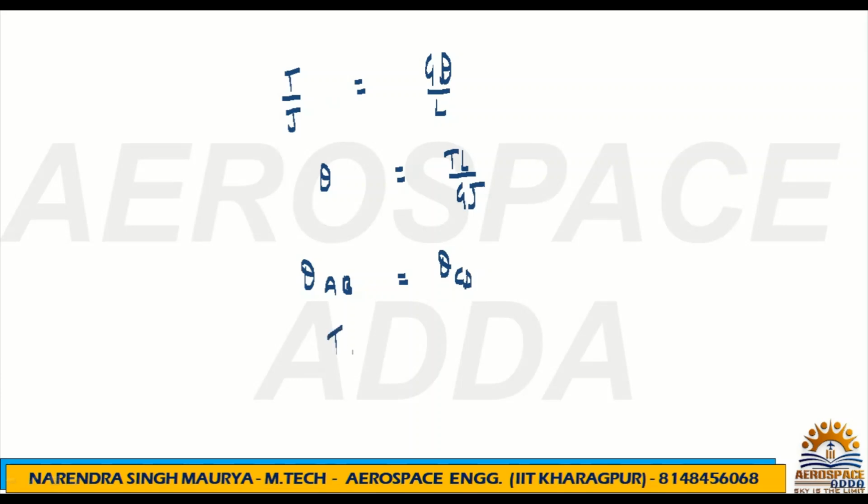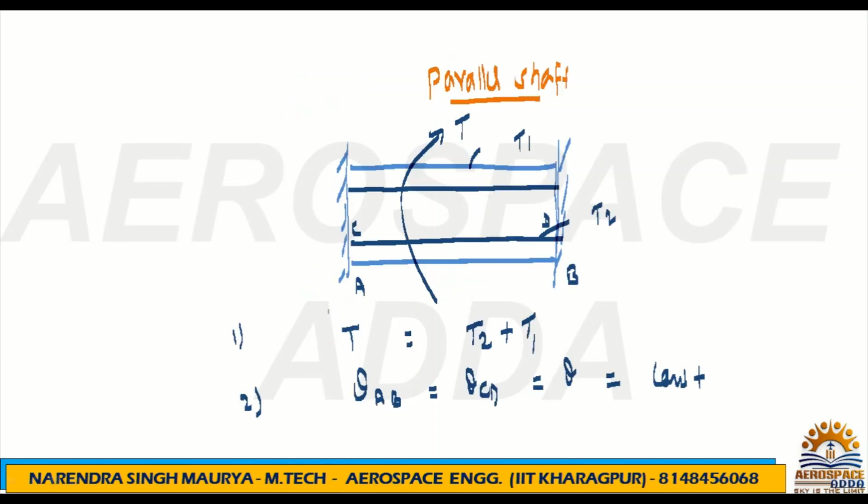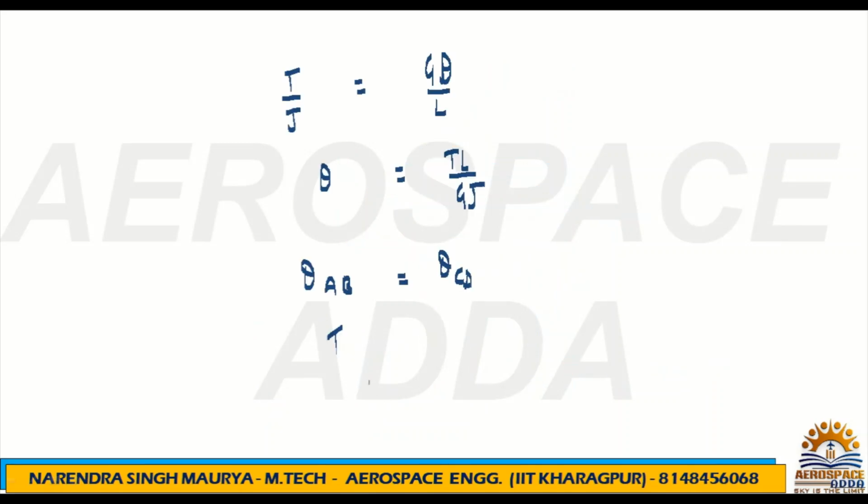First, the AB shaft is the external shaft. It is sharing T1. So T1 divided by G1, since it may be made of a different material, and J1, the polar moment of inertia, because the diameter will be different.